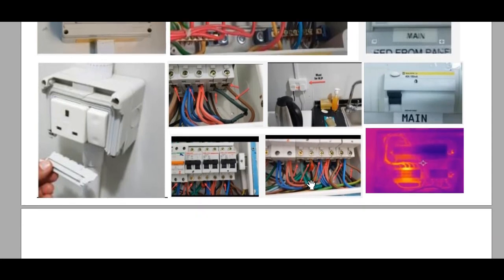Here as you see they use a tape, so this is not allowed here because the tape must be a good type of tape. This tape was open, and also the connection between this part and this part, they used it here for extension because this wire does not reach inside, so therefore they cut it and took another wire and connected it here to reach this connection to this circuit breaker.